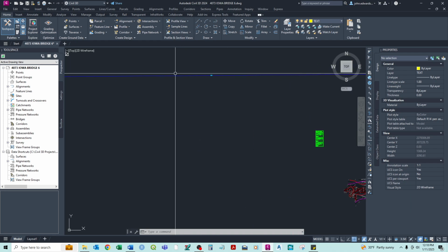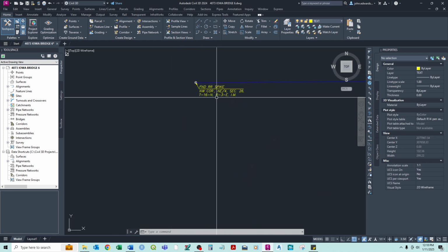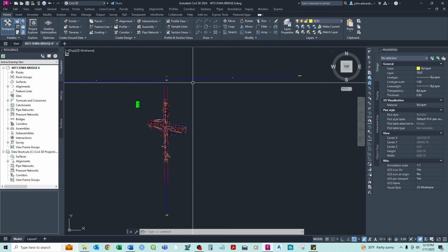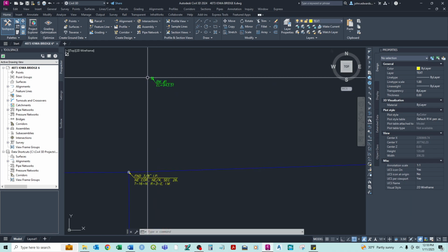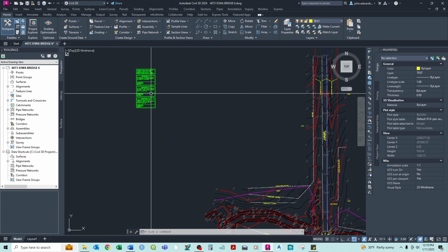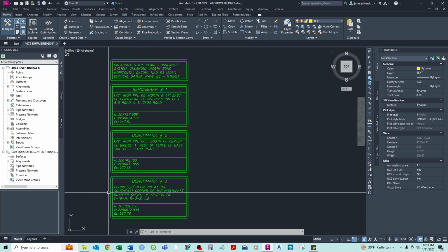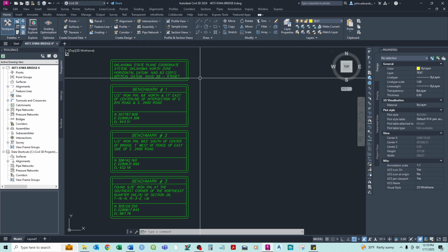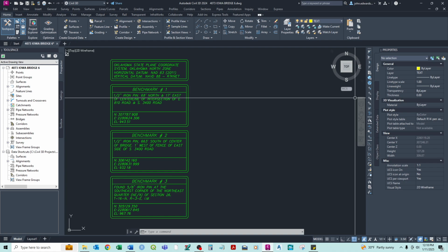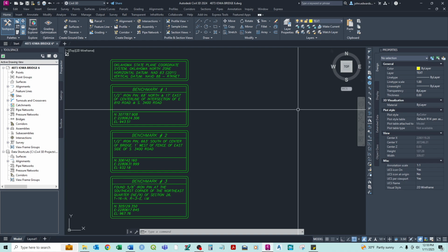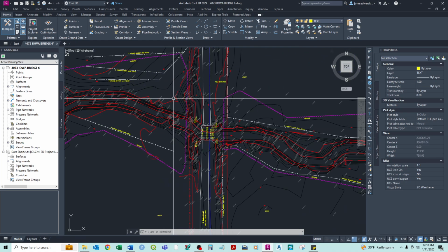And so we can just take a look and make sure we have all the things we need. Normally we have our blue lines, our section corners, which they'll label. These blue lines are the boundaries, section boundaries with bearings. Section corners here. Any benchmarks they have, locations and elevations. Over here we'll have the description of each of these benchmarks, your coordinate system, and projections.